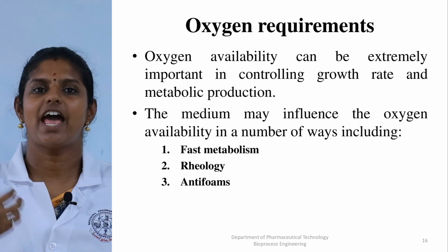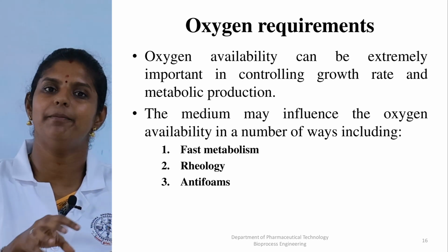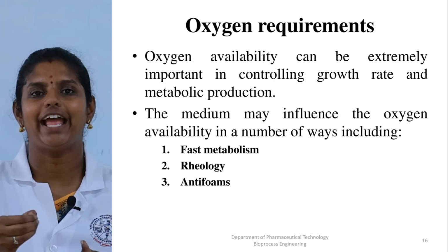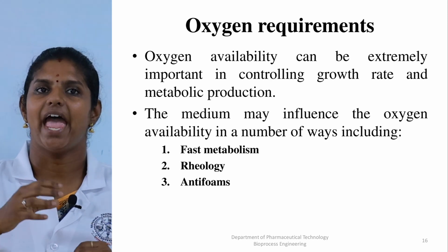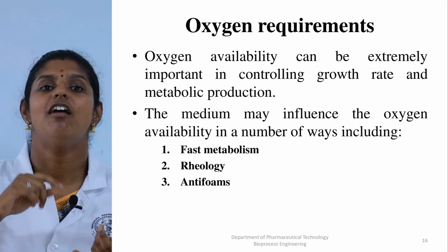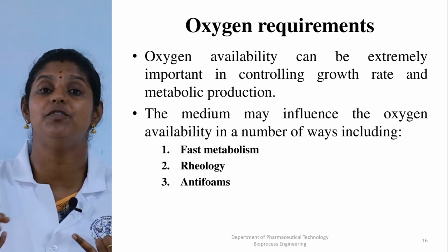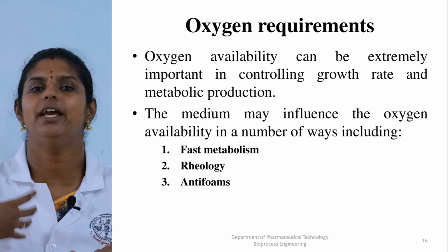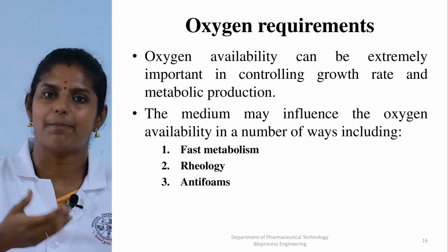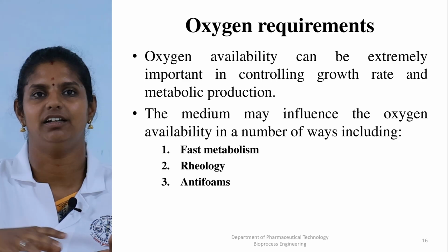And then oxygen. As we have been discussing from the beginning, in the aerobic process the amount of oxygen demand in the fermentation process mainly depends upon the organisms used in the production process, and the availability of oxygen is influenced by the fast metabolism of the organisms. Rheology is nothing but the viscosity of the medium present and how well that medium helps in the production process. And to avoid foams in the supply of oxygen, we also add antifoams, which we already discussed in the oils and fats.